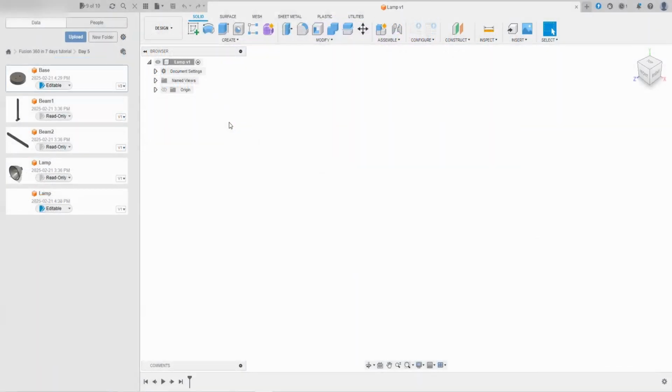If we open up a new Fusion 360 design window, the program always sets up the environment for a new component as denoted by the little cube icon here, which, as mentioned, has its own document settings and origins. However, by adding multiple components to the same environment, the program will treat this collection of components as an assembly. Each component that we add will also have its own environment, setting, and timeline, which will also allow us to easily isolate and modify components on the fly while creating our assemblies.